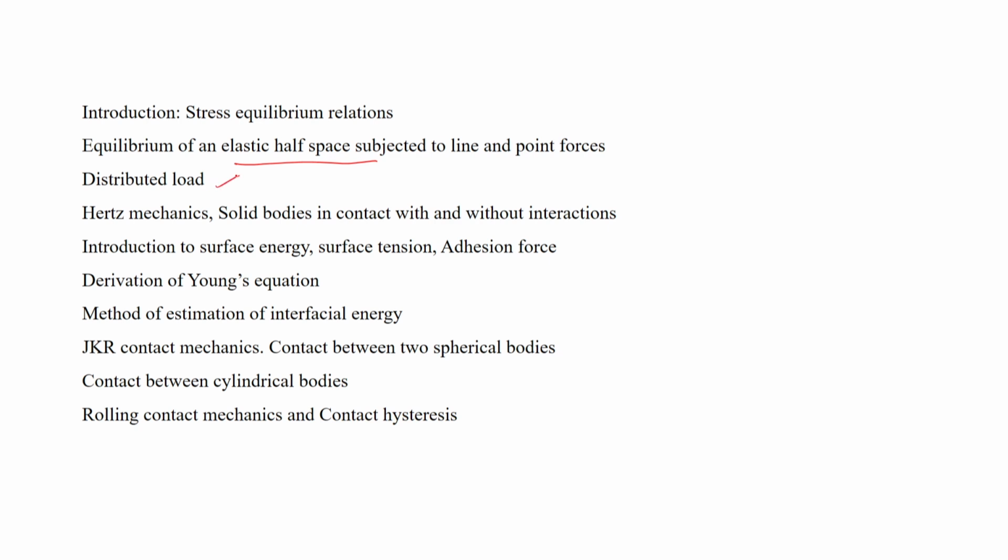I talked about Hertz mechanics, solid bodies in contact with or without interactions, the introduction to surface energy, surface tension and adhesion force. I described in quite some detail how to estimate the interfacial energies and the work of adhesion, the thermodynamic work of adhesion. I also described how to derive Young's equation using Lagrange multipliers, methods of estimation, JKR contact mechanics, contact between two spherical bodies, two cylindrical bodies, and then rolling contact mechanics, and while doing all this, I also described what contact hysteresis is.